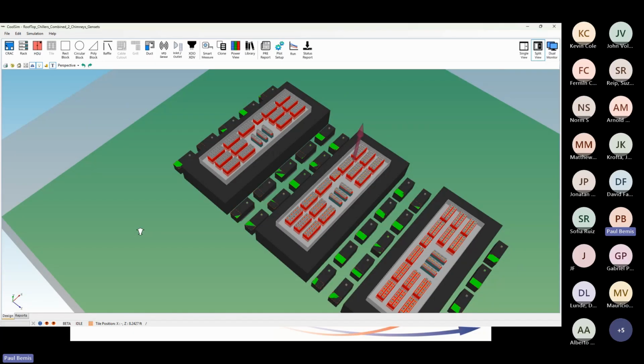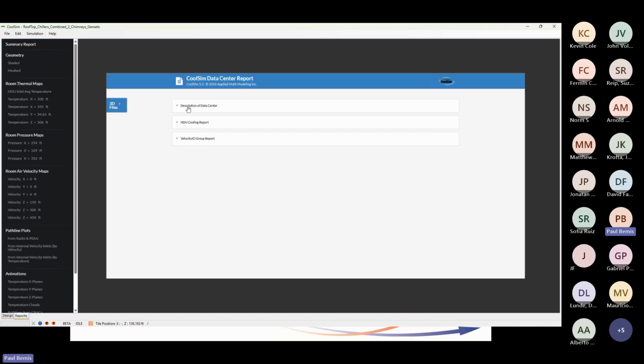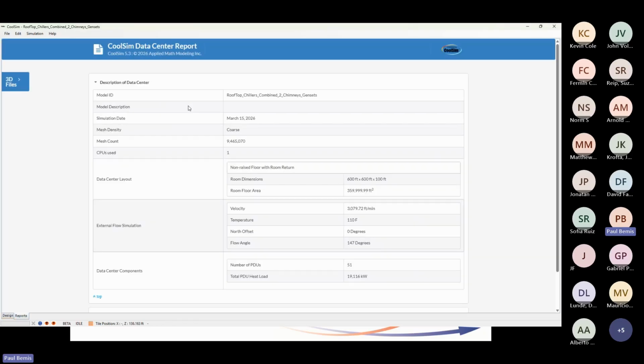So you have to build it right, no gaps. You have to use cloning to make sure that there are no odd separations. It's all about the mesh. In this particular one that I ran, we've got a mesh of 9 million cells. That's not bad, 10 million cells. I think that was a rerun of Post. That one's bigger than that.